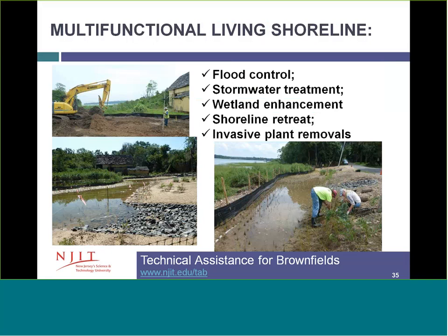That material was all removed. The area was regraded, and we created bioswales in its place, which provides now flood control for the local area, stormwater treatment, wetland enhancement, as well as shoreline retreat. As water levels rise, we now have a natural buffer for the shoreline to retreat back in.